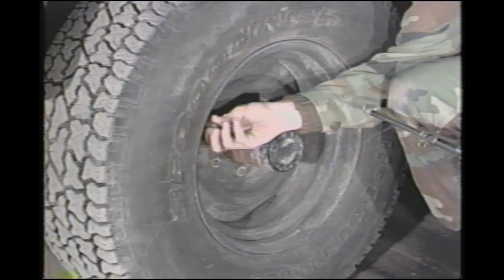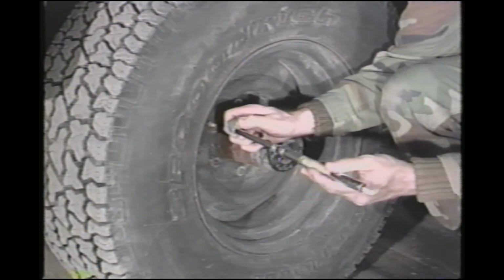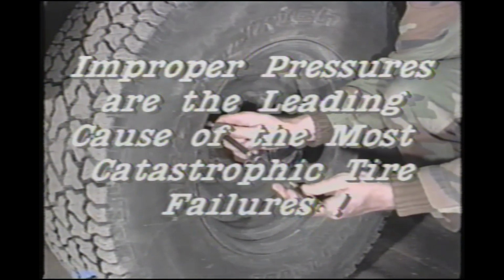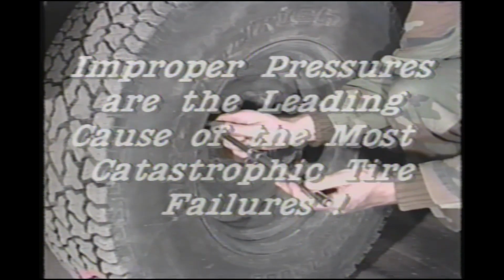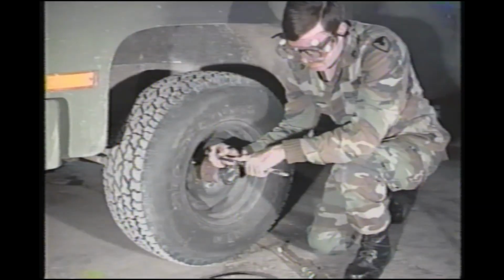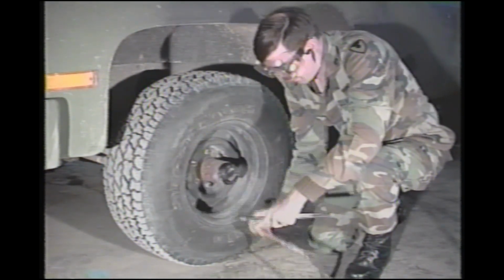Tire pressure is critical to vehicle performance, tire life, and passenger safety. Improper pressures are the leading cause of the most catastrophic tire failures. If the vehicle was recently driven, allow the tires to cool before testing to ensure an accurate reading.